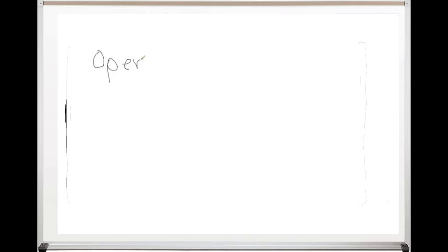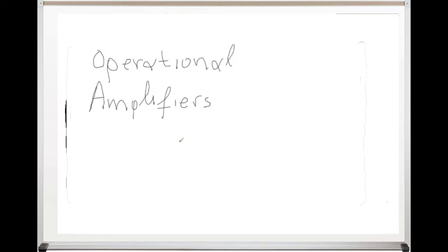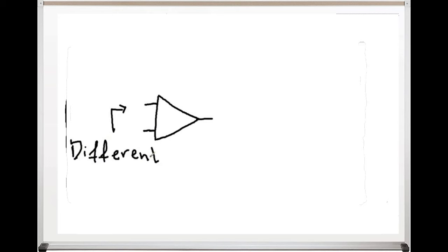What is an op-amp or operational amplifier? Op-amps are differential input amplifiers that are used in electronic circuit design. Modern op-amps are integrated circuits that are small and cheap and therefore find use in many applications. Op-amps have as a circuit component 3 terminals, 2 input terminals and 1 output terminal.